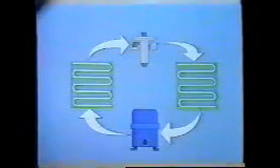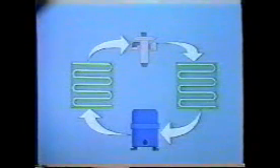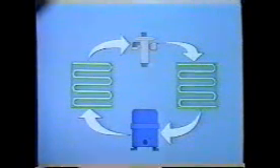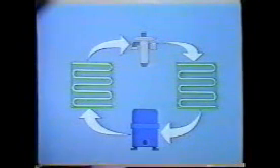The refrigerant liquid flows through the liquid line to the metering device and the evaporator. But as you know, the refrigerant is under low pressure in the evaporator. So how does it change from high to low pressure? By means of the metering device. It might help to think of the metering device as a dividing point in the system between the high and low pressure sides. Metering devices can operate in response to temperature, pressure, or volume.